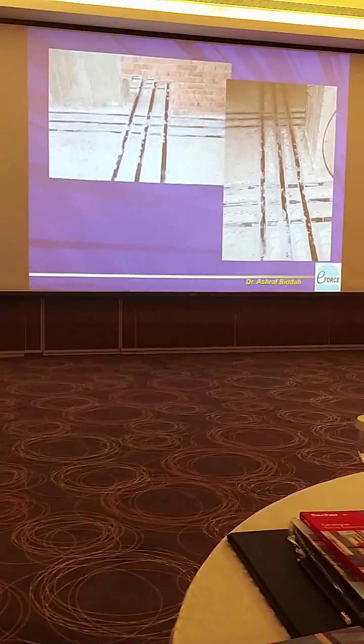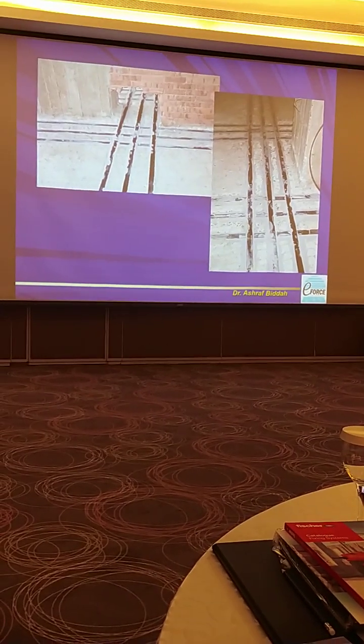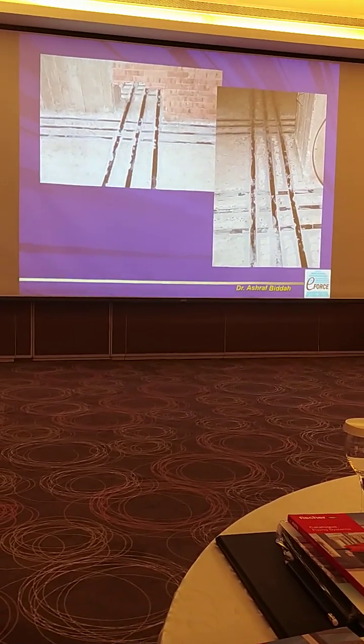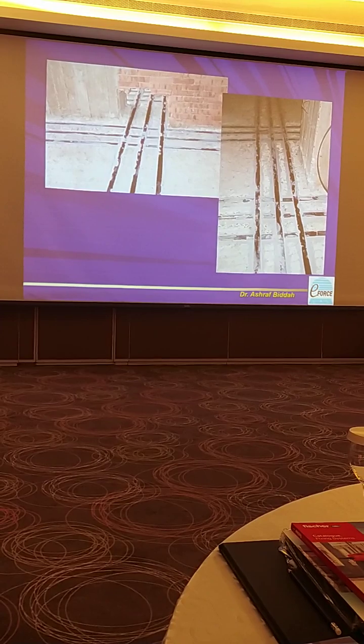From the first impression, everybody can do it, but take care. 50% of this issue is the application. If I glue it to the concrete improperly, this means I did nothing. So I need to make sure it is glued to the concrete in a proper way.